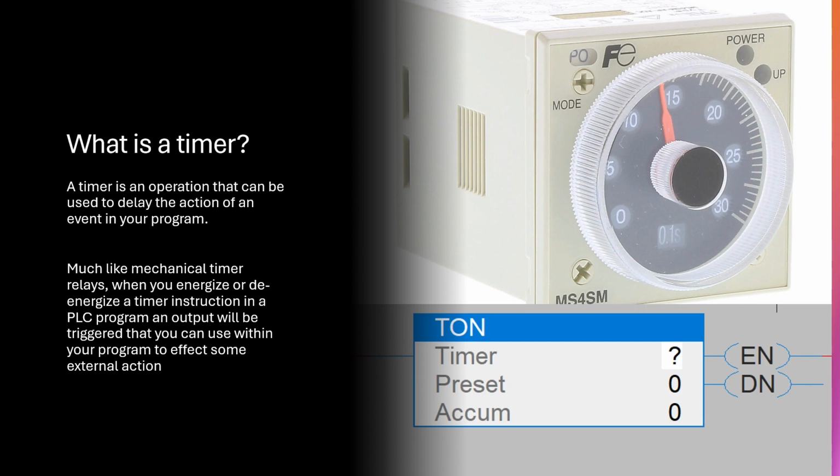if we want to make the timer take longer or adjust automatically to different conditions. Let's say if your conveyor speed is slightly faster than what it normally is, you can actually have in the program somewhere to adjust the timer set point to affect the action at a different time based on your conveyor speed.